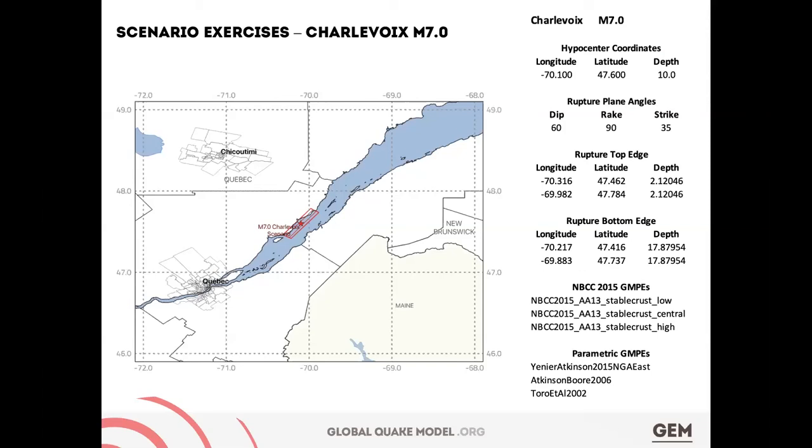So you can model damage using discrete damage states. For each kind of structure, you could define what exactly you mean by slight damage, moderate damage, extensive damage, or complete damage. These would be some measures of damage, and on the y-axis of those functions you're looking at the probability of exceeding each of these increasing levels of damage given the ground shaking. It depends on the type of structure. For masonry structures, slight damage could be the first moment when you start seeing cracks appear in your plaster, or start seeing the falling of the cover concrete in reinforced concrete structures.